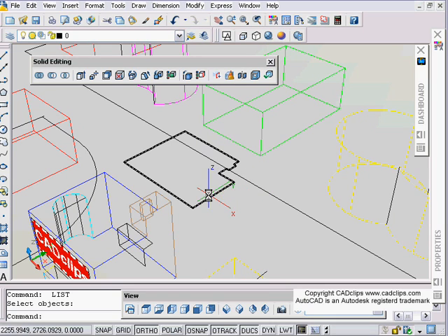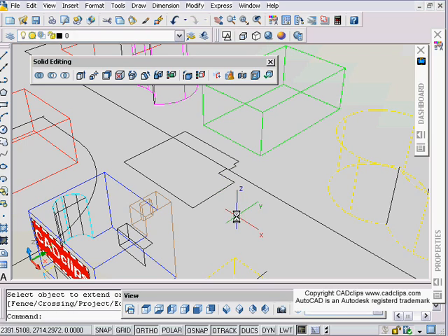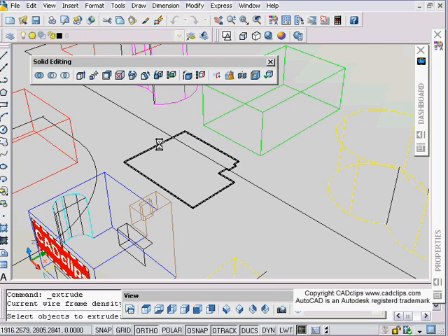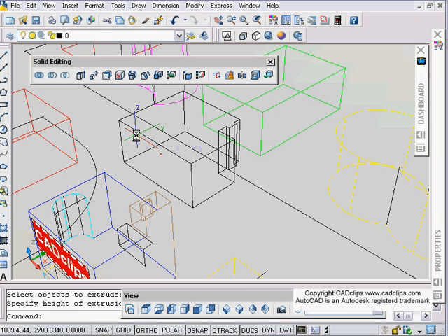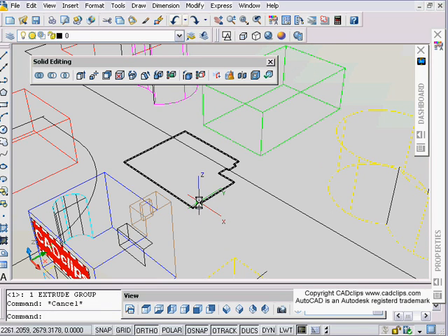And I seem to be struggling here trying to convert this region to a polyline, and I'm just trying to demonstrate some of the different things you can do with the copy face tool. So I think in worst case scenario I'm just going to explode this, or actually what I should do before I explode it is, you can take that, by the way, and you can extrude that as an object to start with. So once you take that shape and you copy the face, you can extrude it. I should point that out before I explode it.